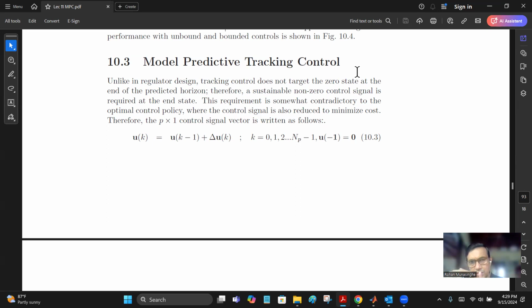We took the first state signal, which is gradually driven to 0 by the linear quadratic regulator, and we input a negative step there, say -1, for example. Then the linear quadratic regulator thinks that it is at -1 now, so it pushes the signal to +1 actually.